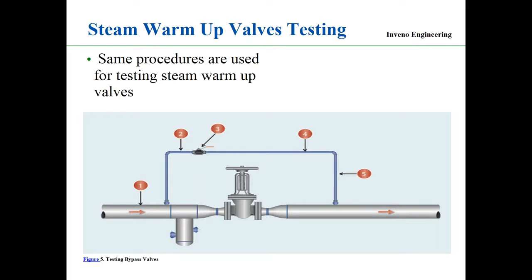So ultrasonic sound is very directional. By taking these points and seeing the increase at the discharge side of the valve, it tells us it's leaking. All ultrasonic levels should be pretty close. Nothing's going to be perfect. They're not going to be 25, 25, 25. Life's not perfect, okay? So as you see, the increase is there because ultrasonic sound is being generated. And that's a quite common process that we use on warm-up valves all the time because we want to make sure that they are in the seated position. Specifically, if we go through a shutdown at the end of the year, we want to make sure we know all the valves that are leaking and get them corrected.